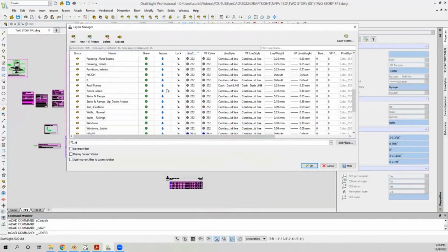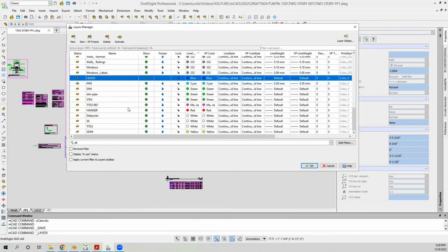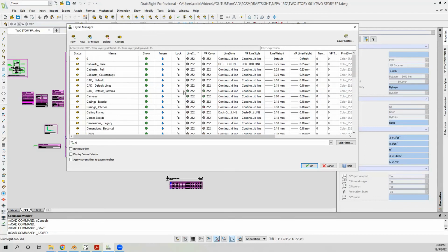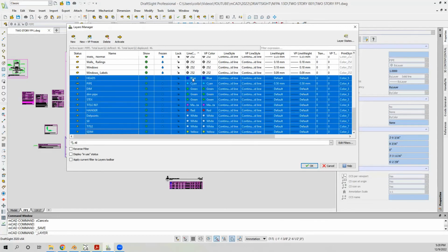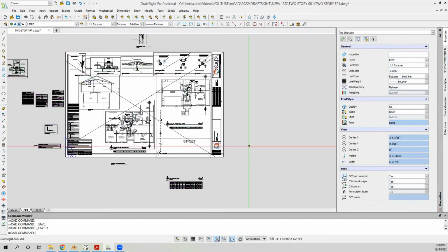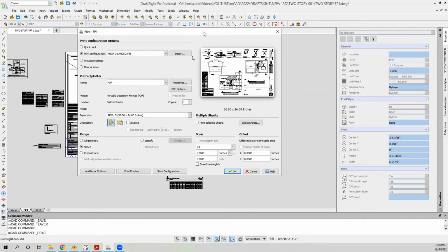There's really lots of ways to plot, but just before I plot, I select, see, I've got all the architectural layers on this 252, which is going to come out and print as a light gray. And I just change our stuff to white, because I have a white background, it'll be black. And I've got two screens going. It keeps bringing stuff up on my other screen.